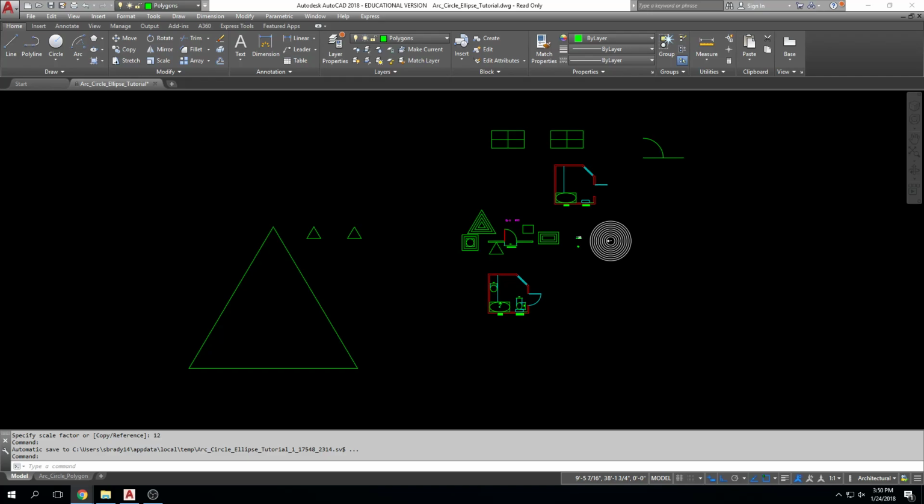If we were to cut at, what is that, maybe 6 or 7 feet, we would maybe see this rail, where we can hang stuff off of, right? So as you cut, you're seeing different things in the floor plans. With a ceiling plan, you're cutting, but you're looking up, right? So there are different rules as to where you cut the floor plate, and if you look down or look up, right? And then you have this other layer of, hey, we make things different pen weights so that visually we can tell what they are on the plans, okay? It's a really fast introduction to that.